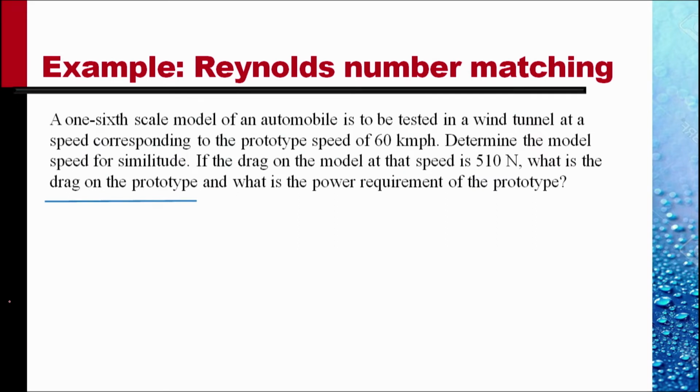We'll apply this to an example. A 1/6 scale model of an automobile is to be tested in a wind tunnel at a speed corresponding to the prototype speed of 60 kilometers per hour. Determine the model speed required for similitude. If the drag on the model at that speed is 510 Newton, what is the drag expected on the prototype, and what is the power requirement of the prototype?